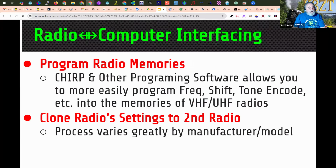You can also program radio memories. Chirp is a very common program to use on VHF and UHF radios. You can use it on some HF radios also. I know I can do it on my 991. I can do memory programming with that. You can also on VHF and UHF set things like shift, tone encode, etc.